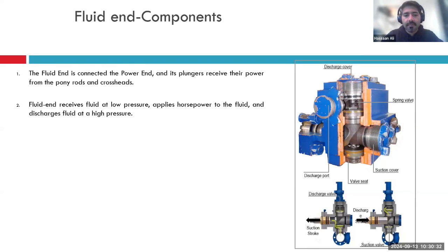On the suction side of this manifold, we are going to see it in the coming slides, but essentially there is a rupture disc. That is to ensure that if there is any overpressure situation during the suction of the pump, you will have some sort of relief or emergency discharge so that it does not damage the pump.